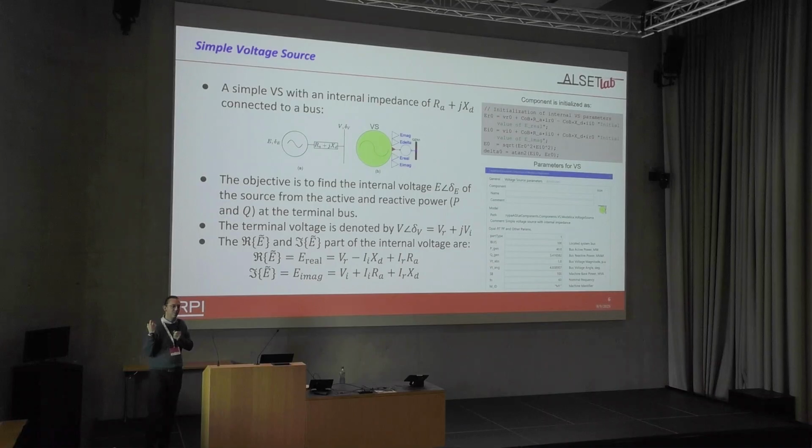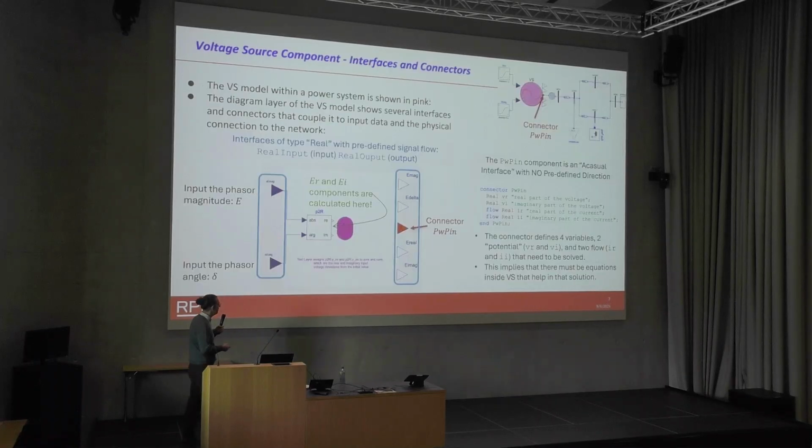the other simulator. The reason is that we do a lot of steady state calculations that have no dynamics involved, which we call a power flow problem. And that helps us provide good start guess data to initialize the dynamics part. So all of these fields that you see here are mandatory fields that are going to be passed by this OPAL-RT simulator. So part type, this is entirely just for their system to work, but you see these parameters are the ones that are required for the correct initialization of everything, basically.